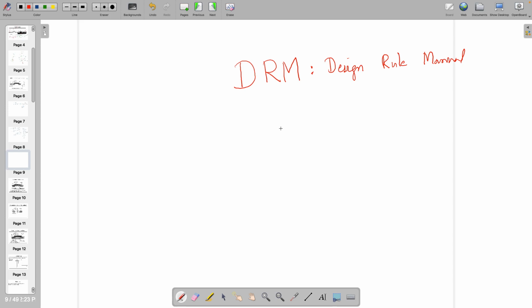You can also find it. It must be available wherever the path from where you are launching Cadence. The path is somewhere fixed, where Cadence and then documents are. In documents you should find it somewhere. This will tell you everything. We don't call it a data sheet, but we call it the design rule manual, which has everything written for that technology. What is allowed, what is not allowed.